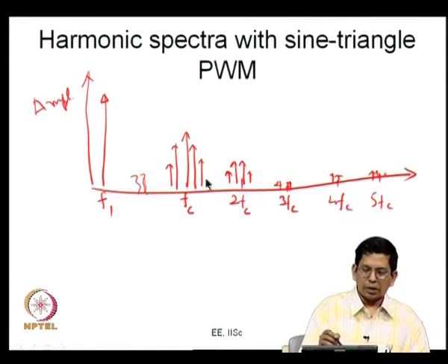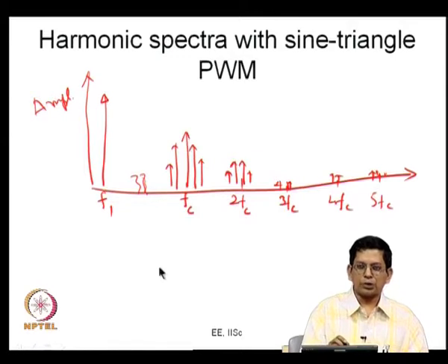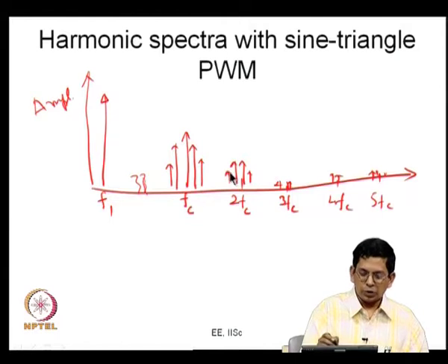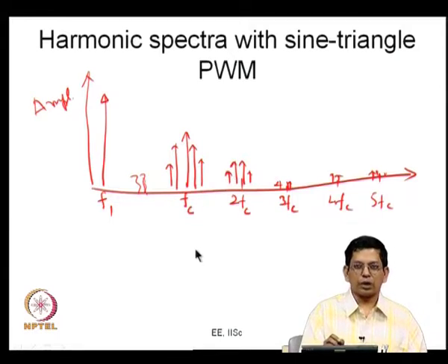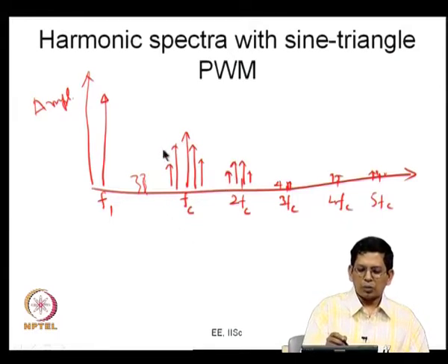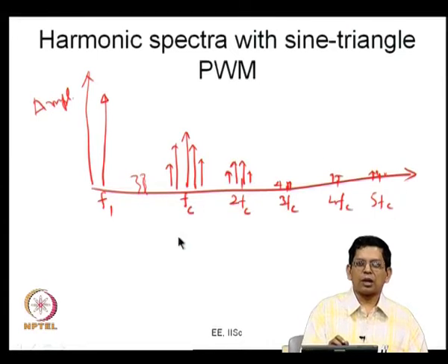What is important is that every frequency component is going to drive a harmonic current of the same frequency. All these harmonic currents can be added up to get an RMS current, the RMS ripple current. What we are interested in, in many situations, is to find out the RMS current ripple. So we would take the route of the space vector approach and do some analysis based on it to come up with the RMS current ripple.